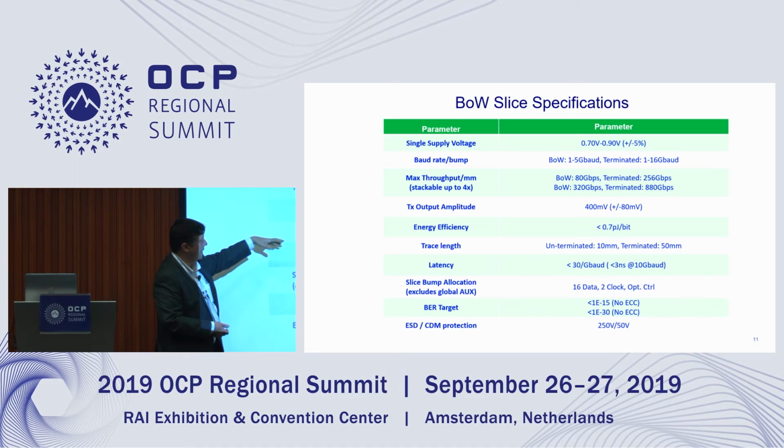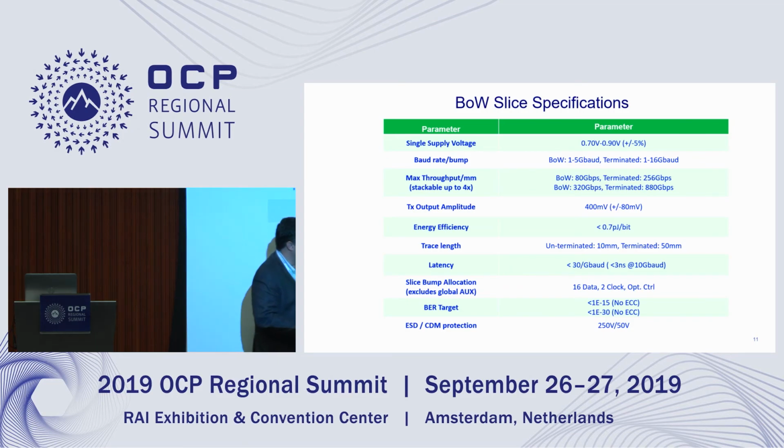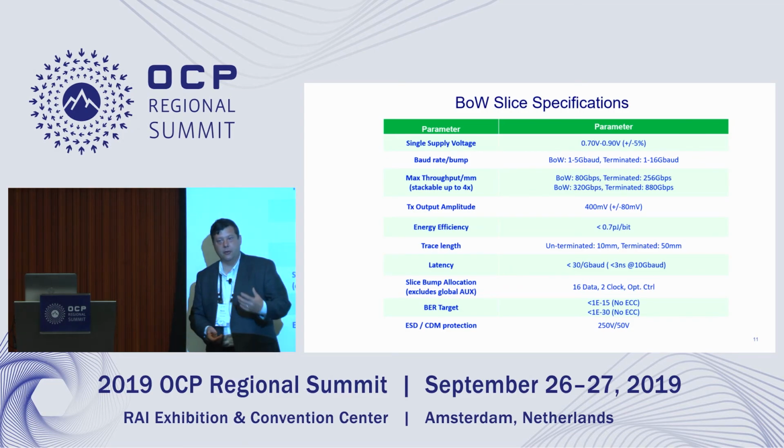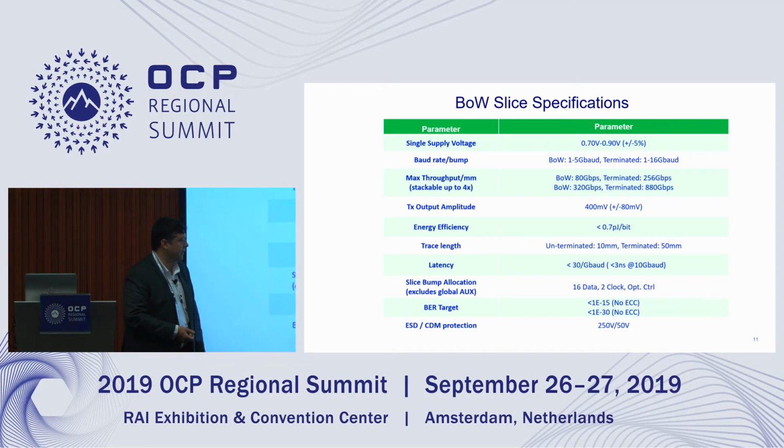I won't go through many more of the details, other than obviously targeting very low latency requirements, corrected bit error rates that are very acceptable with the lightweight FEC that we've recommended. We'll get to bit error rates that are in the orders of thousands of years, so giving a pretty robust interconnect solution for many chiplet-based systems. And simple lightweight ESD, just bridging from standards that we've seen in the industry. On that note, I'm going to ask Eric to come up and just talk through some of the considerations that we've added to the proposal for channel specifications.